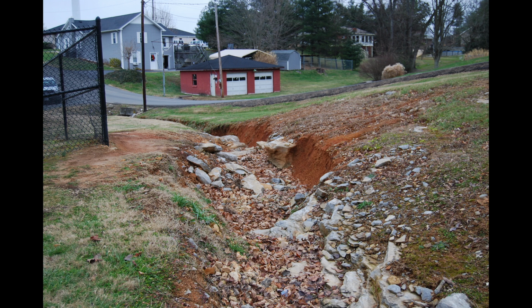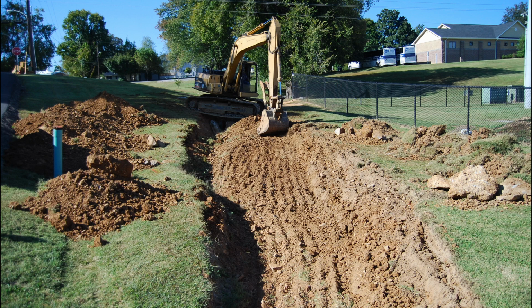He suggested that I use an excavator to remove the soil that was likely to erode down to bedrock, then to create a wider floodplain, and then to slope the banks so they would not erode. I remember him saying that we could control the head cuts and the erosion if we simply removed the soil that was eroding and placed it on higher ground. Art's suggestions were brilliant. It was an easy decision to follow his advice.